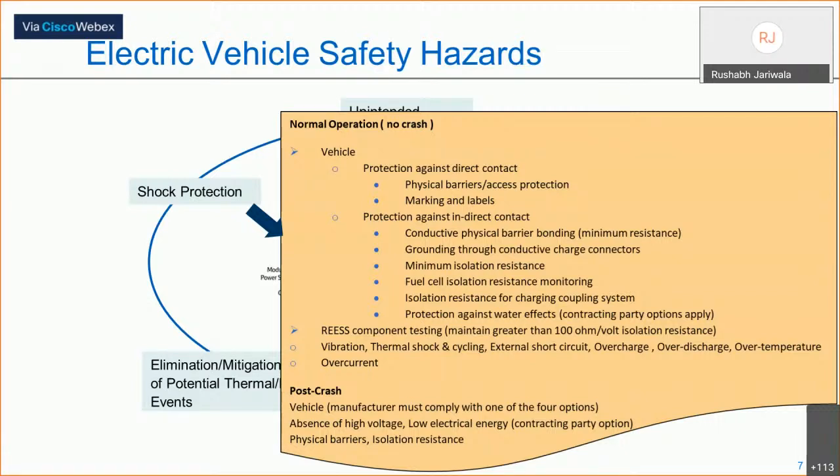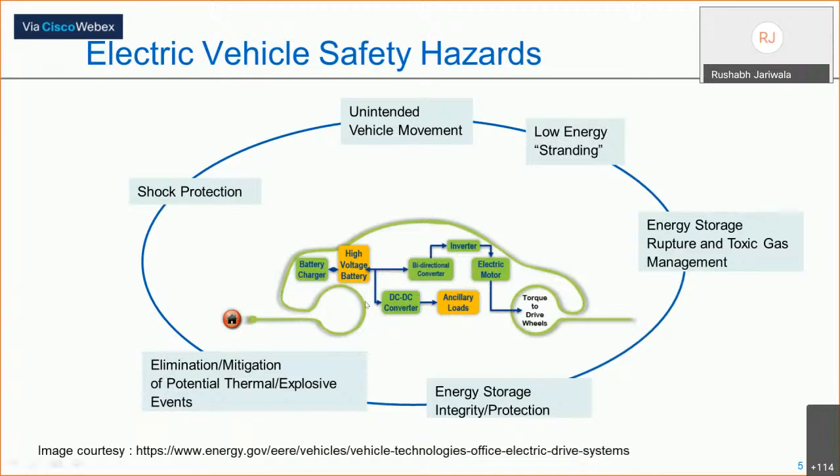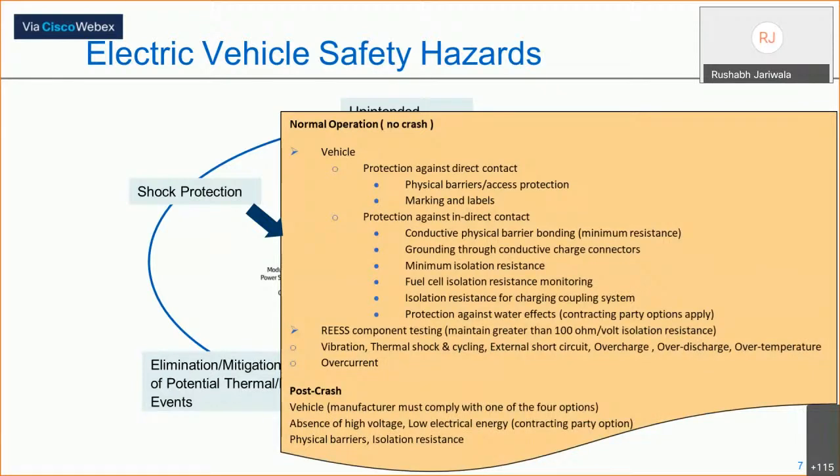But if you lay the battery packs below the passenger area, that seems to be a sweet spot, though there are some challenges with it. Anyway, even the placement of these energy storage components plays a critical role, so that when there is a crash event, it does not get a direct impact.